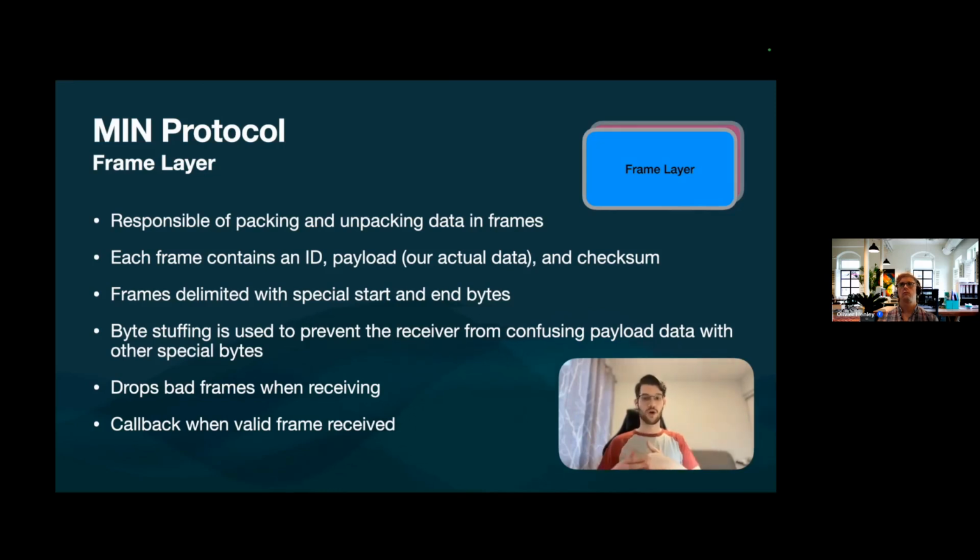So you can choose to always send using the same ID, or you can use a different ID for the various sensors that may be connected to your microcontroller, for example. We also have information about the length of the payload. Obviously, the payload itself is also included in the frame, and at the end of the frame, we also have a checksum, which allows us to perform some basic data integrity checks.